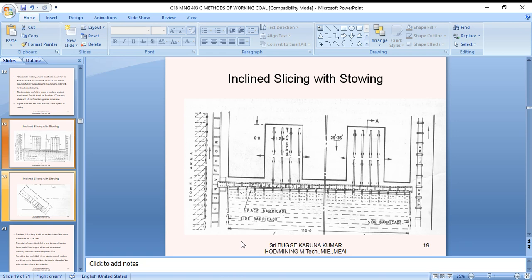The three slices, each 2 meters thick, are taken to the rise simultaneously. The interval between the slices is 50 to 60 meters. Before filling, wooden planks are laid on a rail, and after filling the rail of the artificial roof is removed. In moderately inclined seams the longwall face is advanced to the rise, and in steeply dipping seams the longwall face advances on the strike.